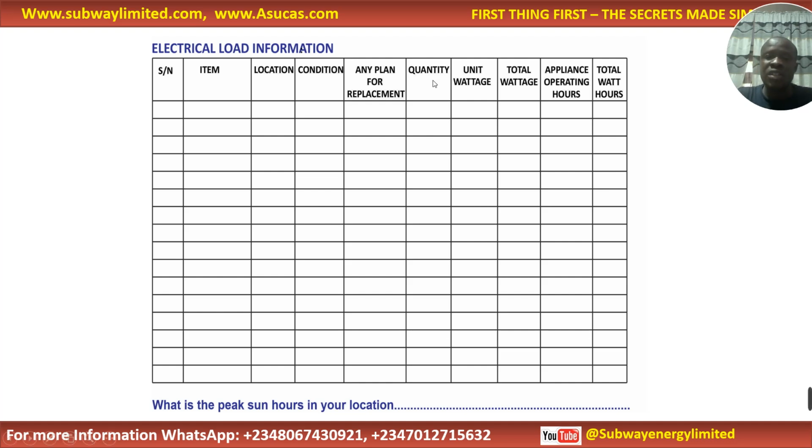Quantity, this column, how many? That means how many do you see? Is it 3? Is it 5? Is it 10? If it is a light bulb, how many? What watts? So the next thing here is the unit watts. Each of the electrical loads that you are auditing, what is the unit watts? This column, quantity, means television, how many? Fridge, how many? AC, how many? That is quantity. So this unit watt talks about what is the rating.